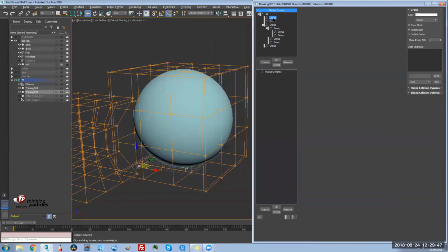The first one we want to call it drive. This is the one that will drive the dynamic elements. And joint drive, this works in conjunction with the drive object. Here we will have all the dynamic elements involved in the bullet physics, so we call it BT for bullet.